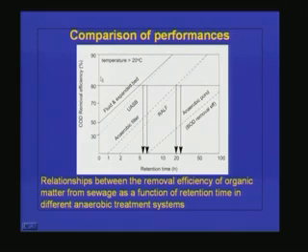So if you want to compare the performance of all these high rate reactors we have discussed so far, we can see that this is the retention time, given in hours, and this is the COD removal efficiency, and this is the fluidized or expanded bed reactor. So we can see that even at very low retention time, the fluidized bed reactor is able to provide a high efficiency.